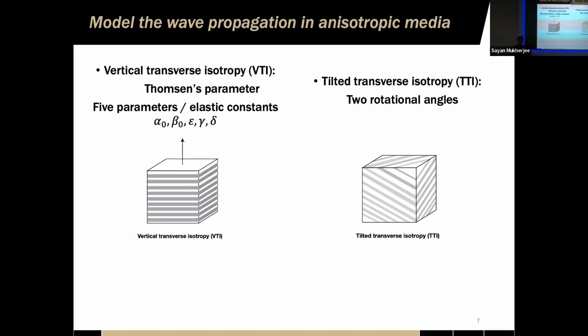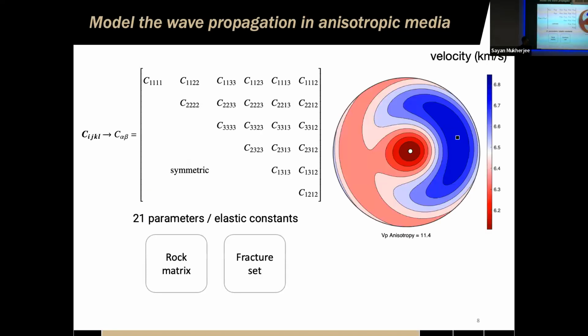And there's maybe, I shouldn't say better way, but a more general and complete way to characterize seismic anisotropy, which is to use the whole stiffness matrix. Even though it's a symmetric matrix itself, it still takes up to 21 independent elastic parameters. As you can see, if we describe the anisotropy with that, the behavior of seismic waves can be really weird and complicated.